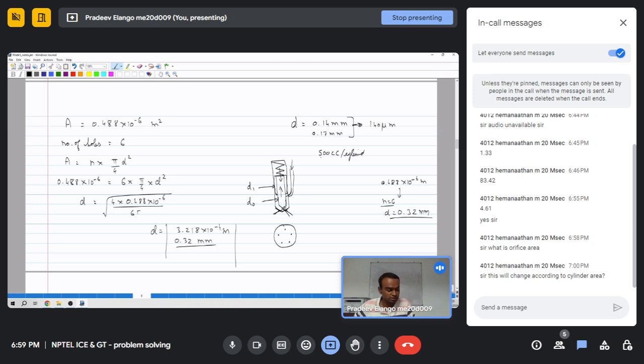So if you have 500 cc per cylinder, and if it is a naturally aspirated engine, then we can calculate how much air theoretically we can get in. Mass of air will be say something like 2 gram per cycle. Now to burn this 2 gram, we can provide some amount of fuel at maximum.